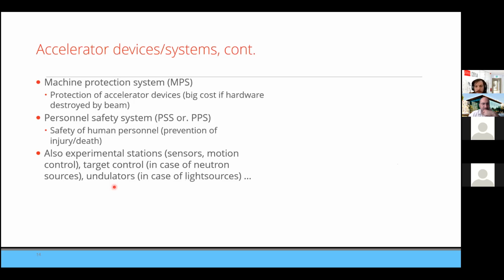So, for example, one cable delay is around 5 microseconds, and you have just a couple of microseconds to respond to prevent damage to the machine. And how to mitigate this issue is basically with the topology of the control system and the network.